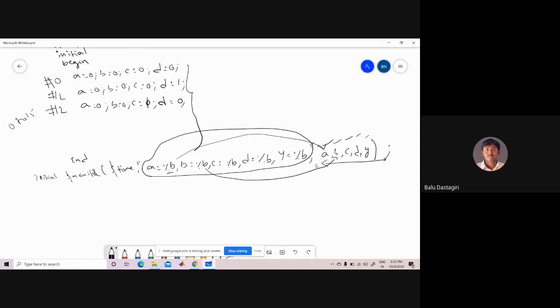After this, next we have to give the simulation time. In order to give the simulation time, give the command initial $stop or $finish, as 100. So I am simulating it for 100 time units. After that, end module.